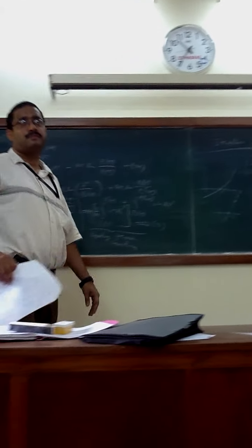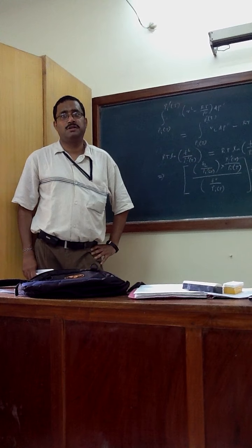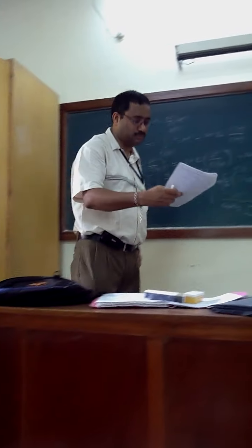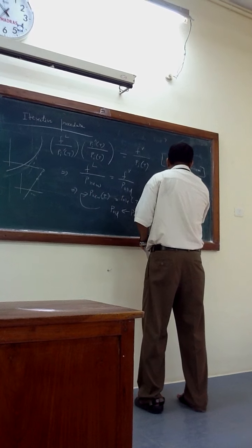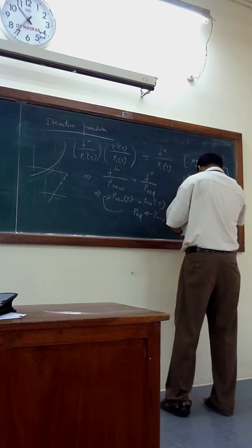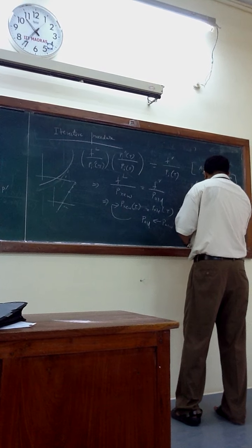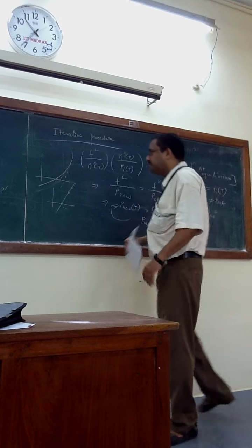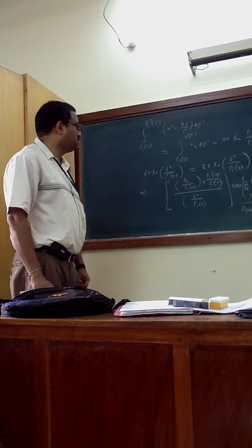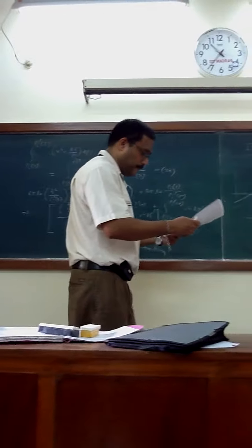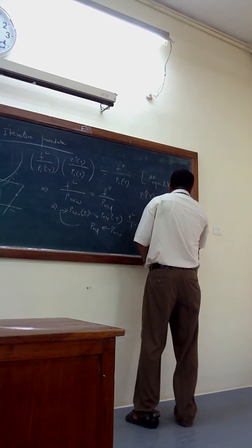Is it not clear? This is the way one can calculate the saturation pressure. It is an iterative process. This is the way one can calculate saturation pressure. So if Pi prime is not equal to P sat, then f_L by f_V sat will be what? If Pi prime is not equal to P sat, what will you get?